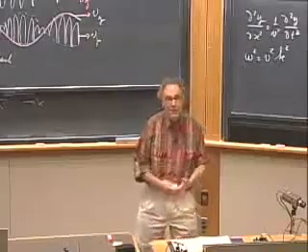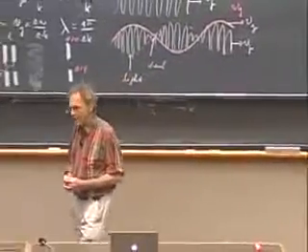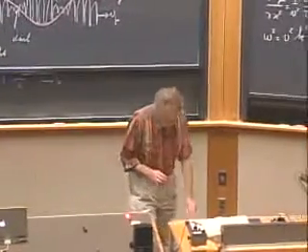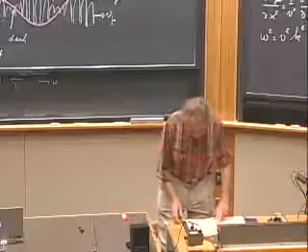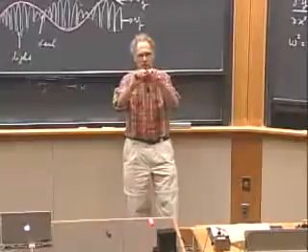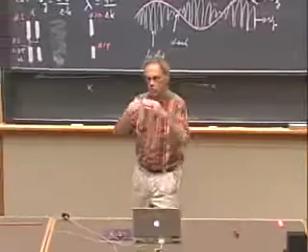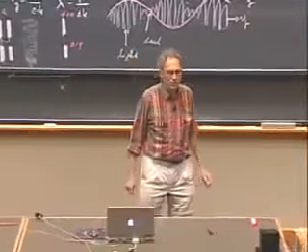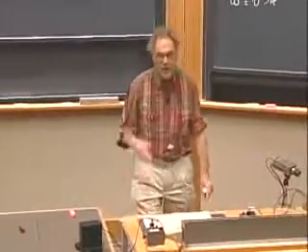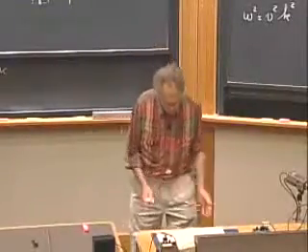However, there is something that we did not take into account, and that is the stiffness of the wire. Imagine for now that the tension is 0. So you take a piano string, or a string from a violin, and assume there is no tension at all. You take it in your hand and you bend it. There's no tension, you just bend it. It wants to straighten out. And that's the result of stiffness. It is due to the stiffness that you get an extra restoring force, which we have ignored. We didn't take that into account.